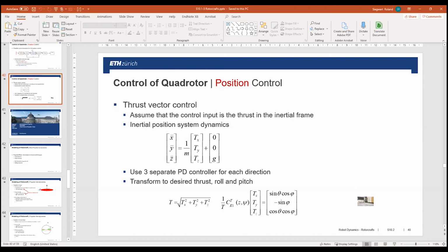There are some questions I probably did not fully understand about this quadrotor or the hexacopter. Of course, if you lose one propeller, you have 5 which are still helping us to hover. So you have to adjust the propeller speed so that you could still hover.